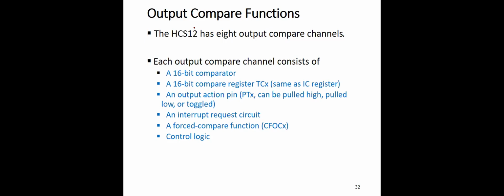No, it doesn't happen automatically. That's why I said you need to define a counter in your program. Whenever you detect an overflow, you increment the counter. As long as you have not received the second edge, you keep incrementing that software counter whenever the timer overflows. Once you receive the second edge, you take the number of overflow incidents and multiply it by the timer overflow time or the cycle time. Okay. So you get how many times the timer in seconds. Then you add T2 minus T1.